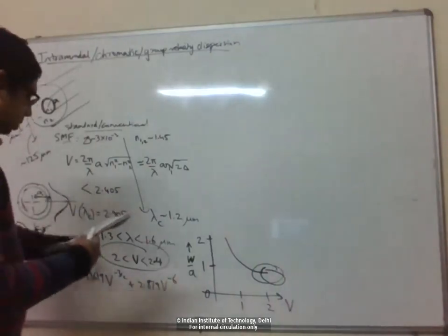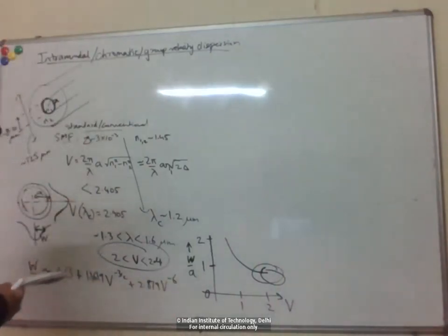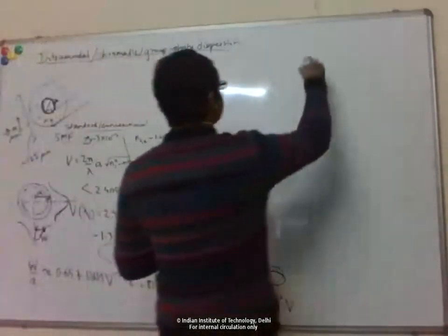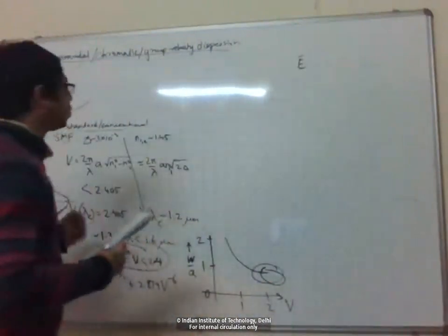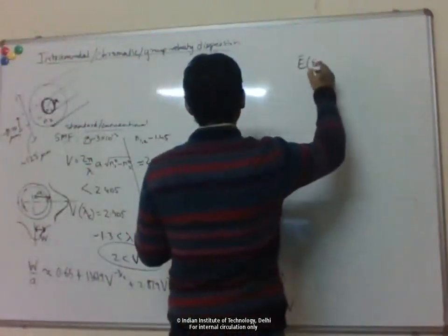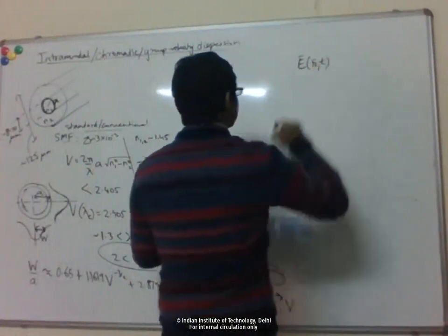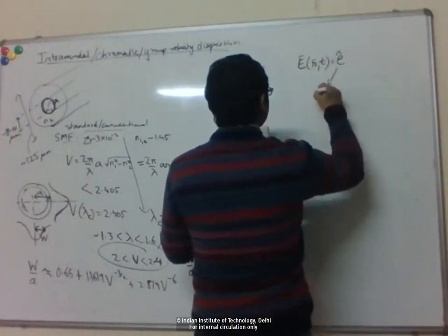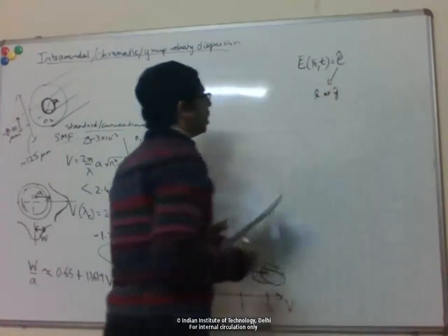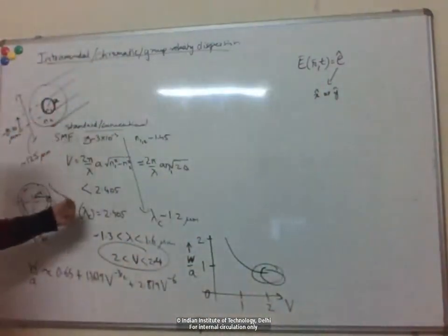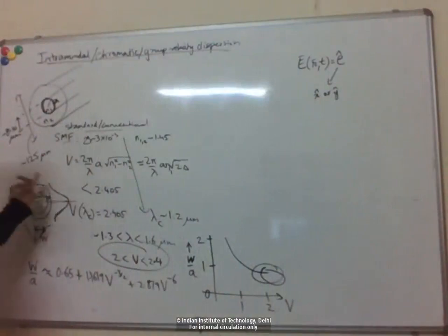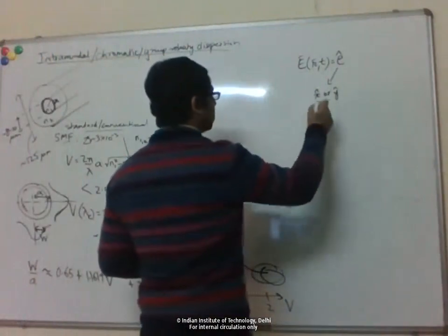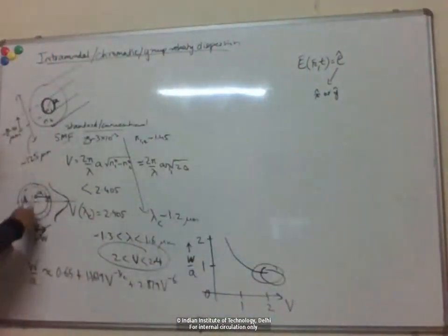Fundamentally, where is this chromatic dispersion coming from? We can write the electric field profile as a function of position and time. There is some polarization. Recall that the fundamental mode here is the so-called LP01 mode, and there are two degenerate polarizations, with the field pointing in either the x direction or the y direction.